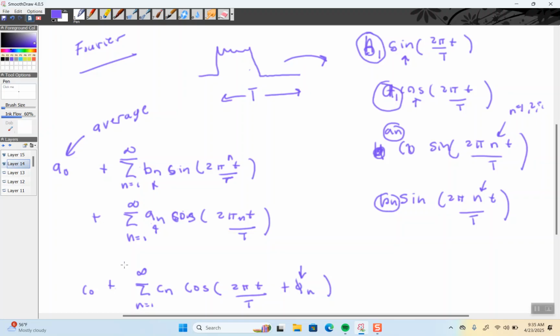All right. So if you think about it, how will a low pass filter react to this? Well, I could do it in LTSpice or something like that, but there are frequencies. I can break this up into frequencies, and then everything we've ever done with a single frequency operates across the whole spectrum.